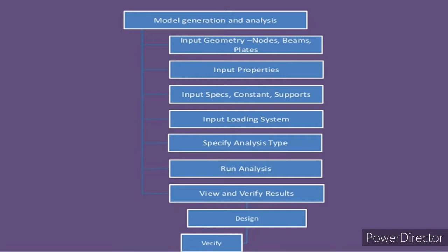This is the procedure for designing of building elements. First one, model generation and analysis. Input geometry: nodes, beams, plates. Input properties, input spaces, constants, supports. Input loading system, specify analysis type, run analysis, verify results, design, verify.